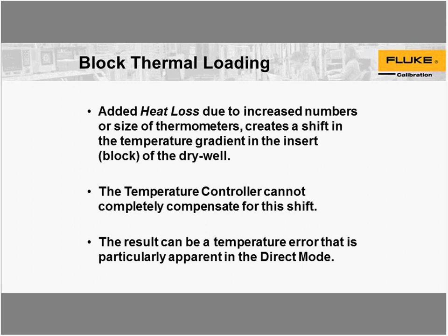The controller will compensate for that. What's going to happen is it will re-zero itself to the temperature that has been the set point. So there's a little bit of a shift, then the display is still going to read what that point was.